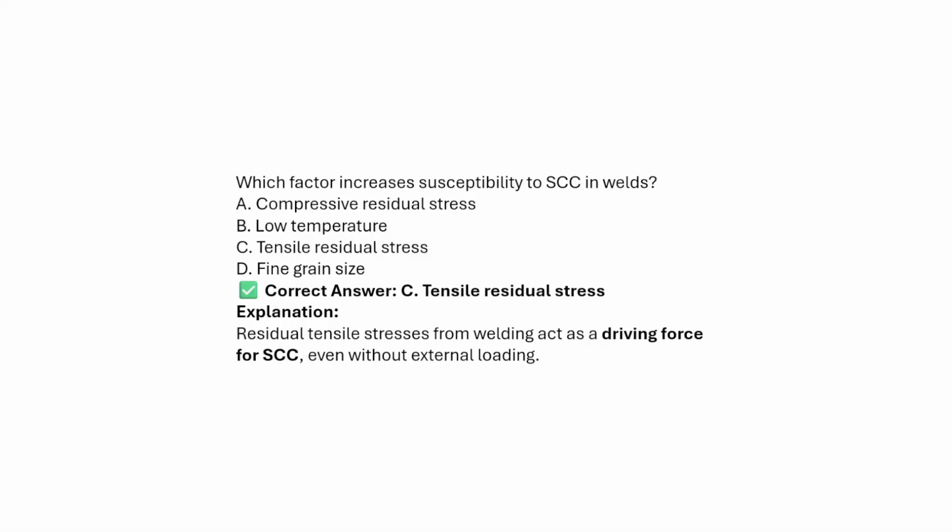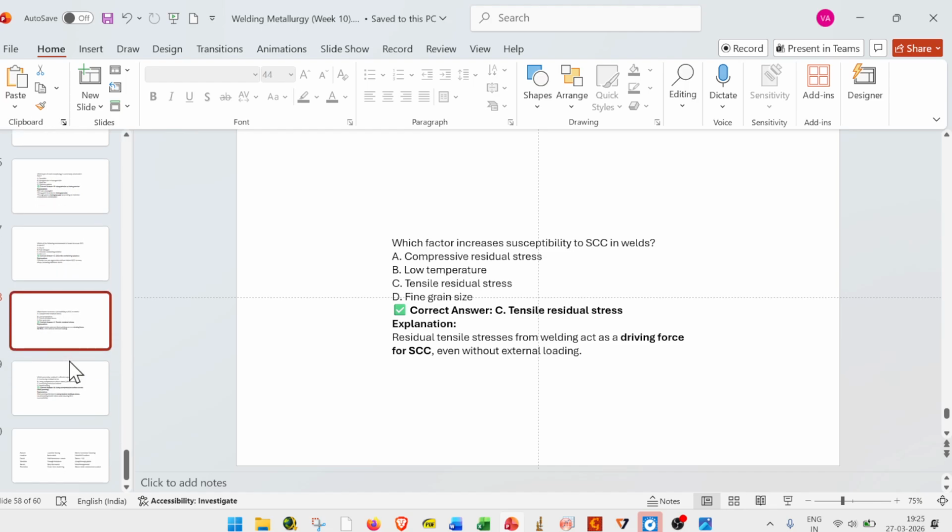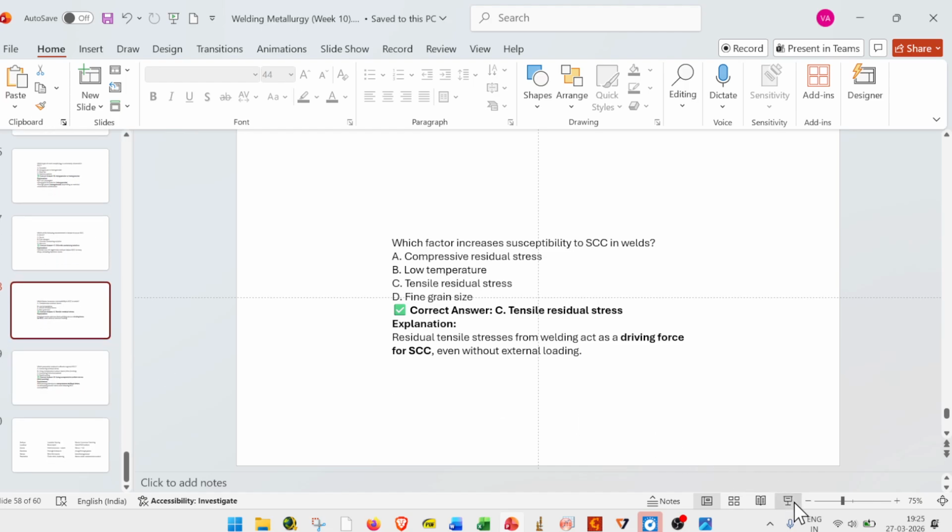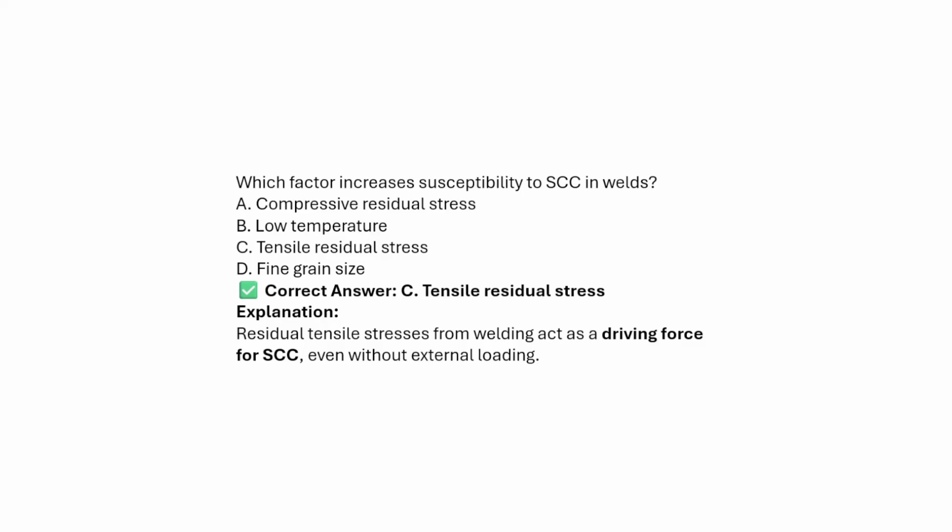So the answer will be tensile residual stresses. Why? Residual tensile stresses from welding act as a driving force for stress corrosion cracking even without external loading.